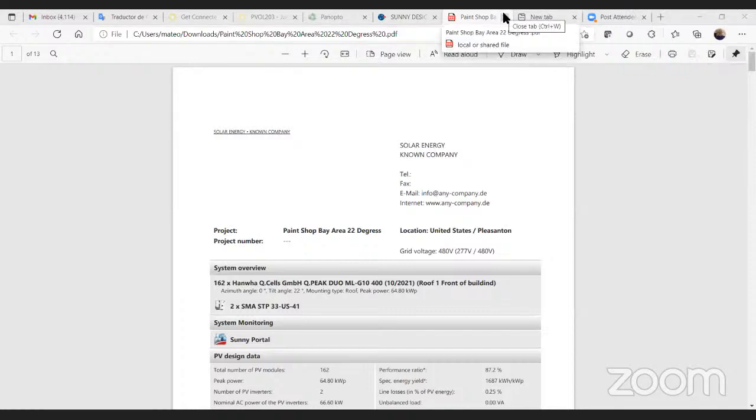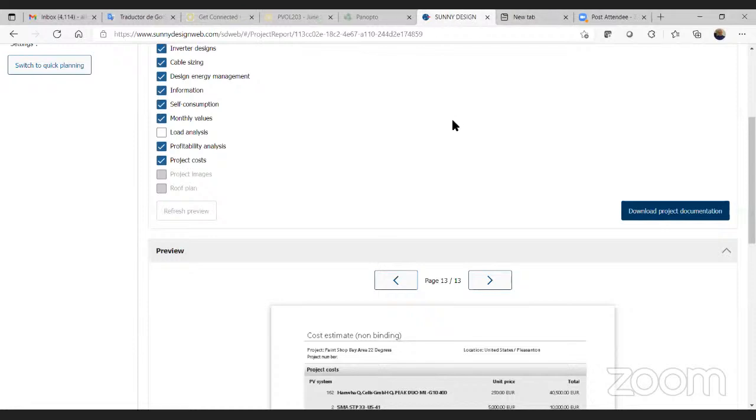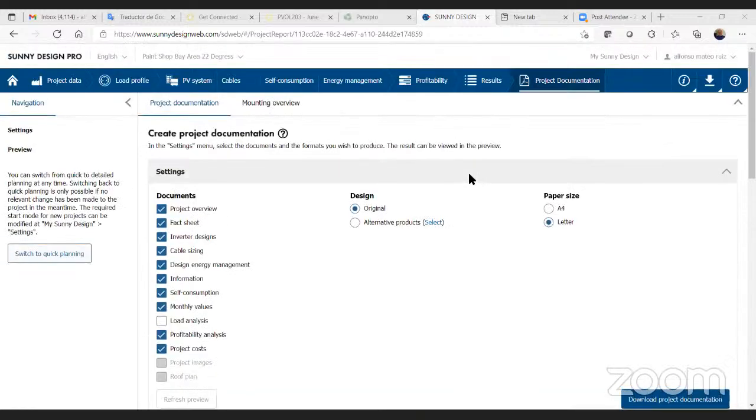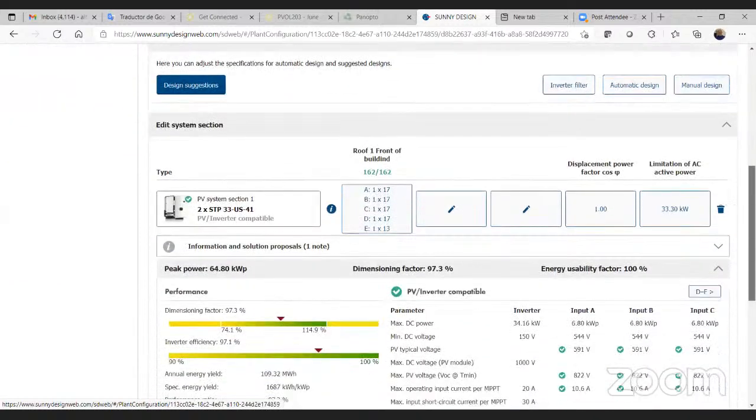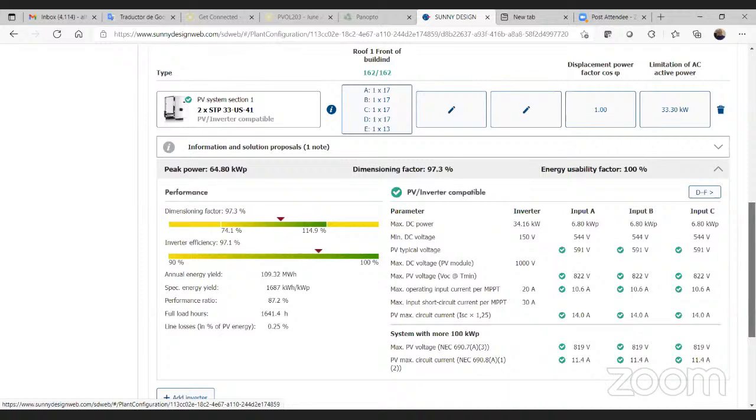So generally, I think the market is seeing lots more high current modules, particularly bifacial modules. And as Alfonso showed in the inverter results, on the Core One, there are 6 independent tracking channel inputs, and the IMP limit per channel or string for any of those 6 is 20 amps. What that means is the inverter will safely hold at 20 amps should the inputs be able to produce more, as long as that 30 amp short circuit current limit is never exceeded. So depending on how much current the modules can make, and this really comes into question with bifacial modules, because it's the installation location that can dramatically change whether a customer would expect to see a 10% or a 30% backside gain from those modules.